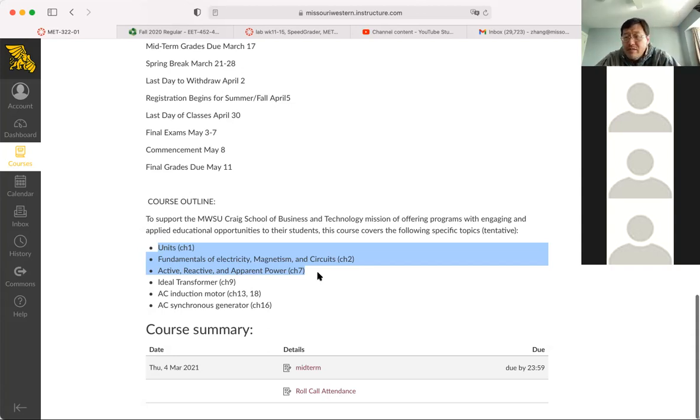And then we plug into power. When we plug into power, we use a complex number to represent power. And then we calculate the current. The current will be another complex number called a phasor: current phasor, voltage phasor, and impedance. So everything is simplified mathematically. And again, after that, instead of solving a differential equation, we just solve a linear equation.